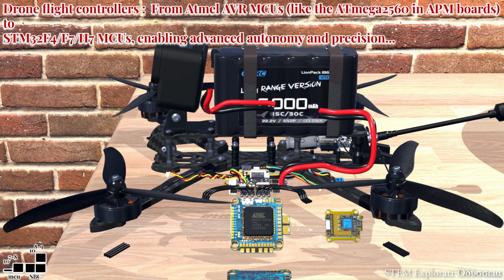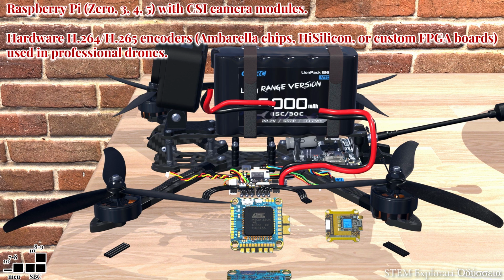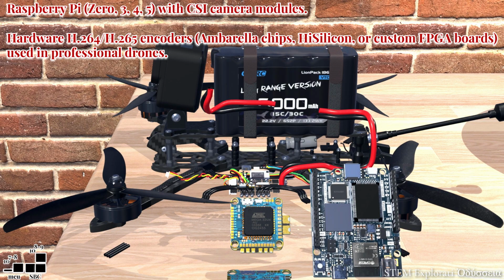But when you step into advanced features, like streaming high-definition video, performing onboard image recognition, or autonomous navigation, the processing requirements jump dramatically. Video encoding or computer vision is far beyond what a standard MCU can handle. For those tasks, manufacturers often add more powerful companion boards or single-board computers, such as the Raspberry Pi, the NVIDIA Jetson Nano, or specialized system-on-a-chip encoder boards. These work alongside the flight microcontroller, offloading the heavy lifting for tasks like HD video streaming or AI-based object detection.